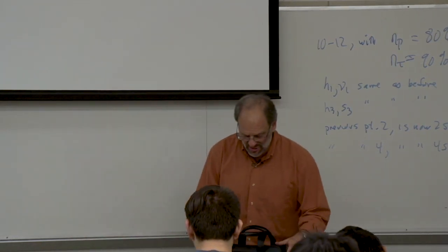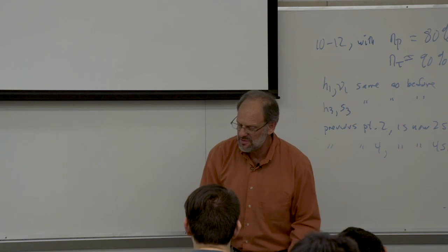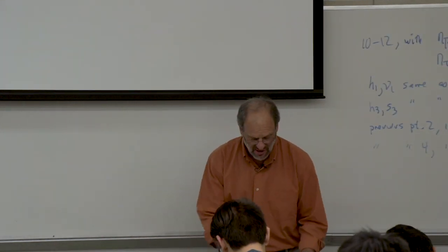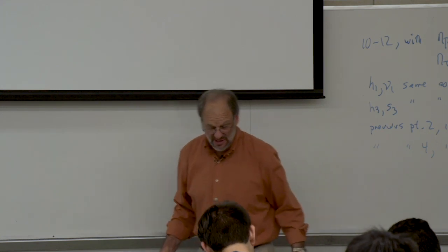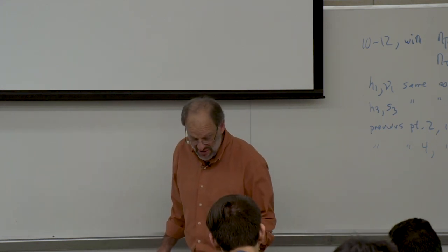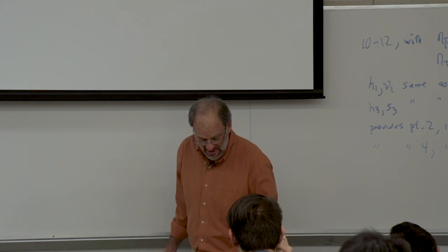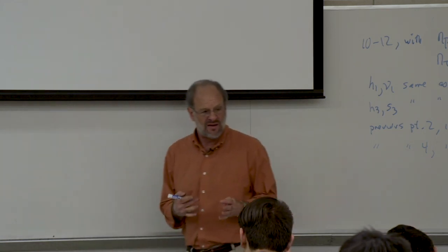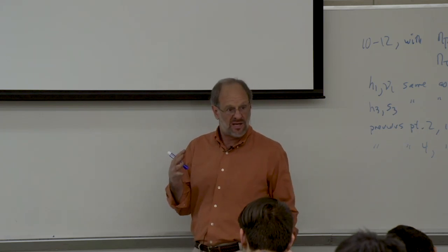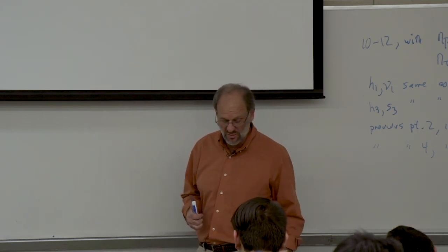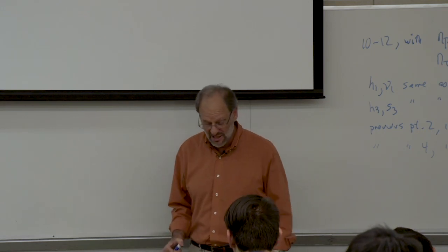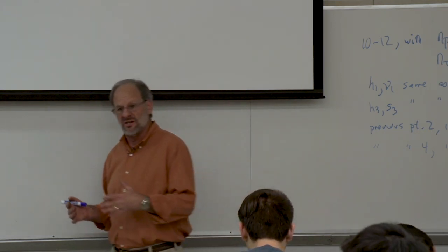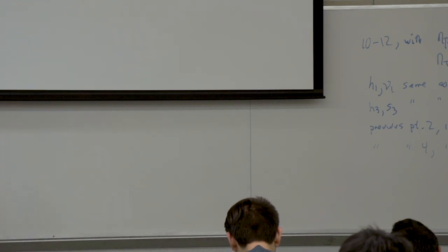Okay. Please note that the numbers are noticeably different. In this particular case, our net work is about 10% or so less. The heat input is also a little bit less because we end up having a somewhat higher enthalpy coming out of the pump than if we assumed that it was ideal. But still, the net effect is a reduction in the thermodynamic efficiency, which is what we'd expect.